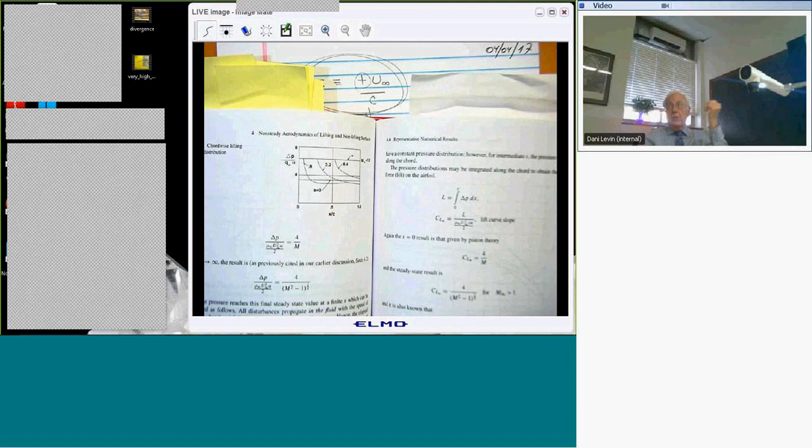The other disturbance that is really going that way is moving at U infinity minus the speed of sound, right? But if I wait long enough, it's moving this way, U infinity minus a infinity, relative to the airfoil. If I wait long enough, the disturbance at the leading edge goes off the airfoil.